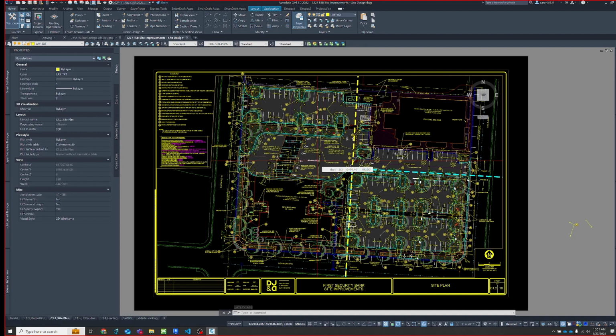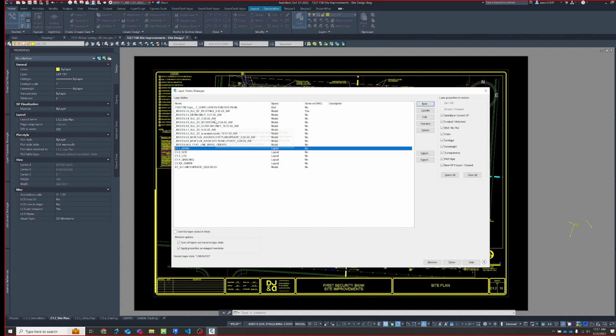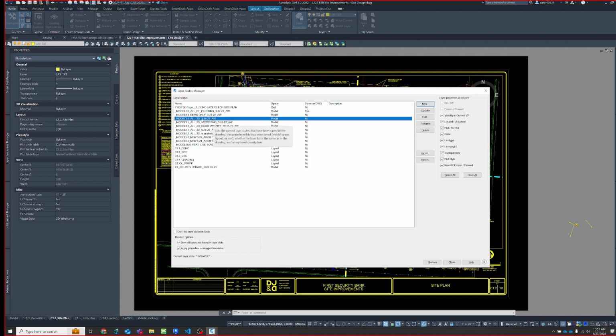So I'm ensuring that this site plan, I can always go back to it. If someone comes in my model, flips a couple layers on and off, leaves without thinking about it, I always have a home base to go to: this is how I plotted it 2 weeks ago. The naming gets a little important. I go a little further with this. I say what it is. These ones not as much, but I'll put that it's in model space. I'll put when I saved it, and I'll put my initials. You can do however you want, but it certainly has helped me in my career, putting something that makes sense so you can remember what you did in these snapshots of layer states to go back to.